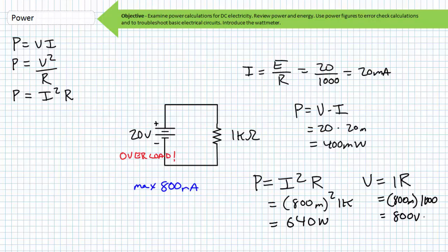Or does it? Recall, our power supply is current limited. Use Ohm's law to determine why the current is unusually high. An unusually high current is indicative of a low resistance path. Can you figure out what is wrong with the circuit now? There's an errant short in parallel with it. Either some extra wire is in there, or you're using your protoboard incorrectly.